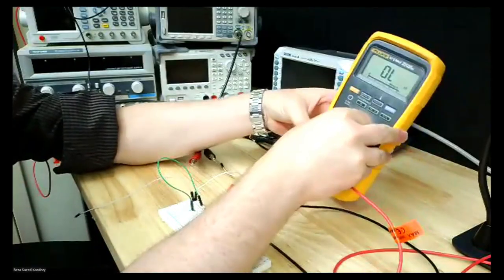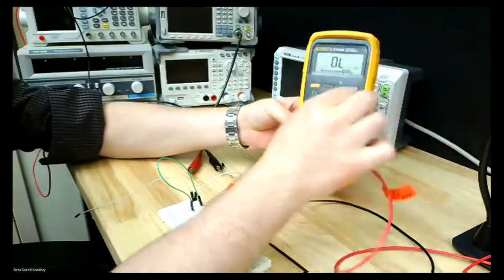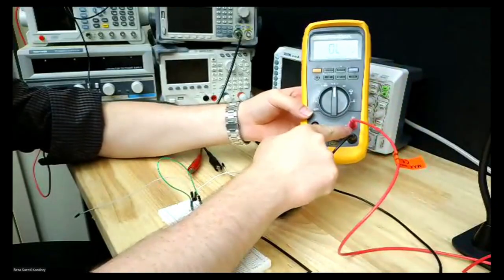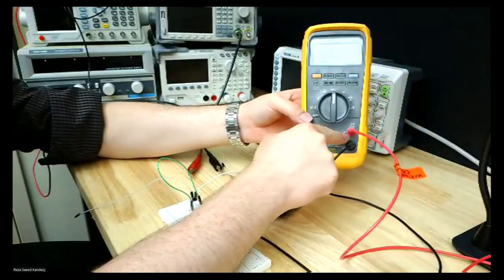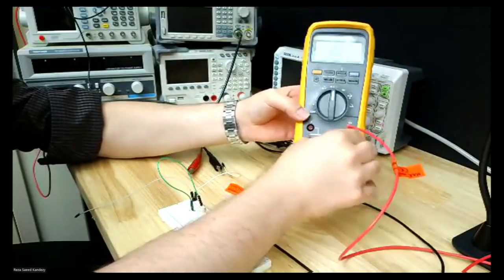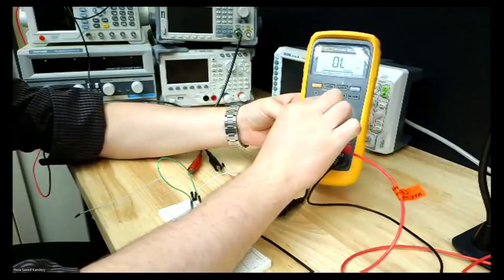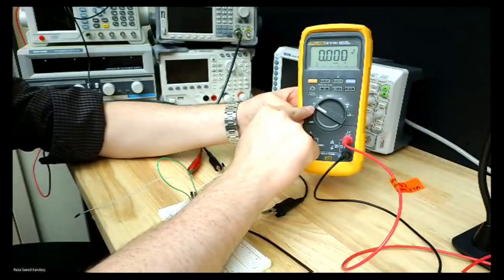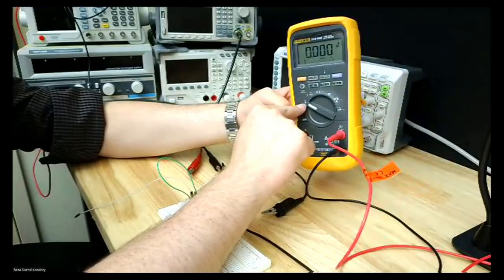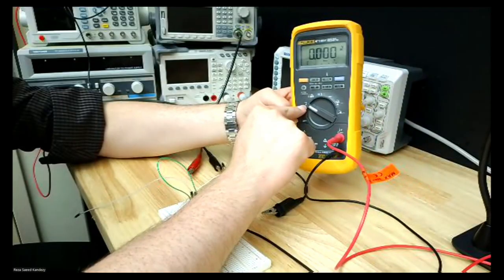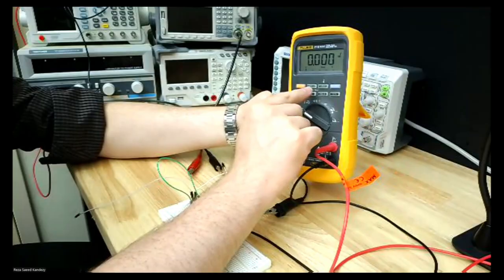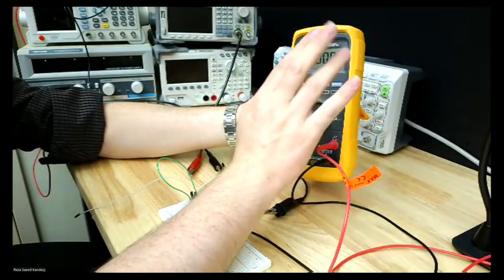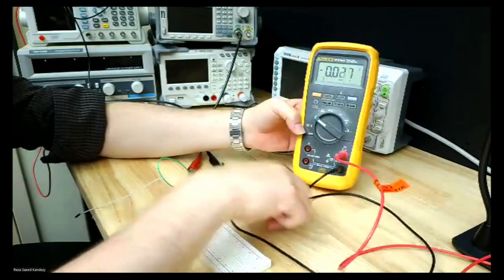I want to have a DC voltage meter. So it's the same probe, because the measuring probe of ohm and volt are the same, and we don't change the common probe. So we are gonna set the value to volt, okay, DC volt, and it's gonna be in a 1 volt range, so we don't need to change the range.